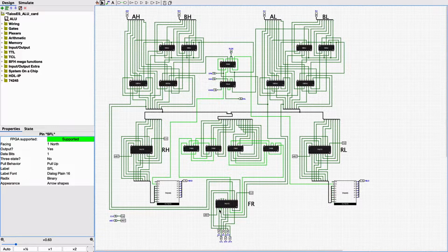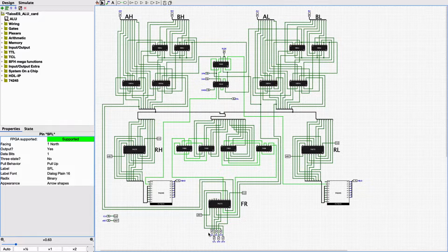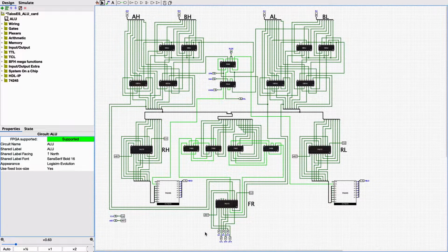It goes in there, comes out in here, sign flag low, and it just tells you whether the result is negative. If you've done a subtraction and you expect a negative result, it tells you whether the result is negative or not. If the result is in 2's complement notation, then the most significant bit is the sign bit. If it's high, it means it's a negative number.